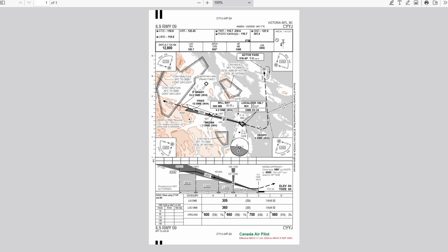or the VOR radio navigation, which will get you into the proximity of the airport, and that works like spokes on a wheel. The radio navigation doesn't just tell you what direction the station's at, it tells you what degree or angle you are from it. So it can allow you to follow a fixed radial in or away from the radio station. Say you can tune it into 270 degrees, and it'll tell you whether you're going off to the left or right of it, whether you're flying towards or away from the station.